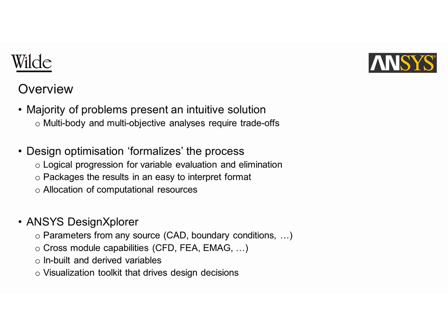Within DesignXplorer itself, we can take parameters from CAD models, and this includes external CAD packages like Autodesk, SolidWorks, etc. We can work with boundary conditions. We can work with engineering data, so yield strengths, Poisson's ratio, for example. It's also, being an ANSYS module, got the ability to talk through the entire ANSYS suite. So be that in CFD, in FEA, in EMAG, and explicit dynamics. And this is something I'll show you as we go through the presentation.